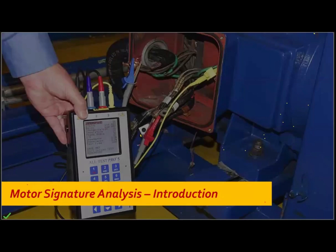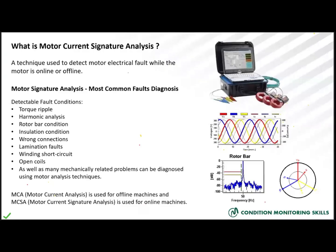And finally, we are going to give an introduction to the fifth most commonly used condition monitoring technique, which is motor signature analysis. Simply, motor signature analysis acquires the motor current and voltage signal without any interruption in production, and analyzes the drive signals to identify many different types of faults. The data can be acquired from the motor control panel, enabling easy testing of remote, inaccessible, or maybe hazardous areas of motors.